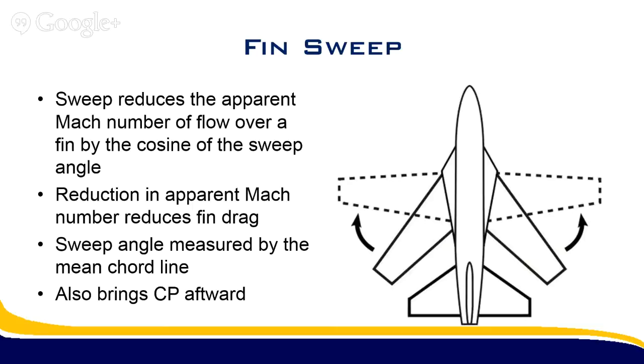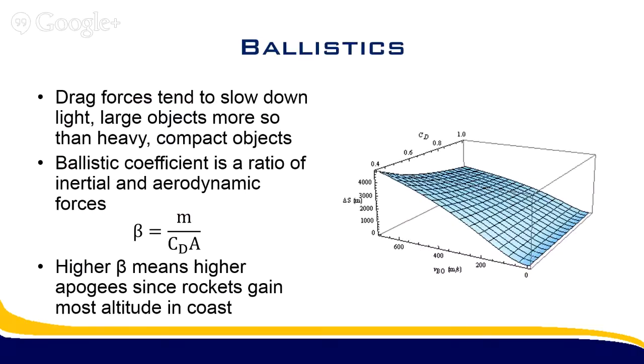Another interesting thing that sweeping your fins does is it brings the center of pressure aftward. That's just moving that fin surface backwards. So that's a plus. Another thing I want to talk about is ballistics, and it's exactly what it sounds like.